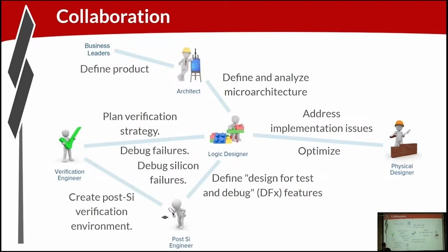And the post-silicon engineer does a lot of preparation, working with the logic designers to feed in features, referred to as design for debug and test, to make sure those features are in the RTL model.